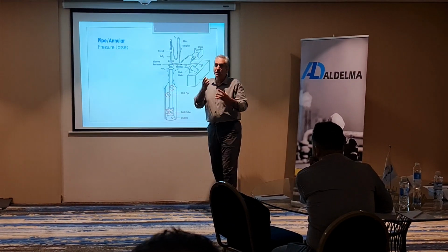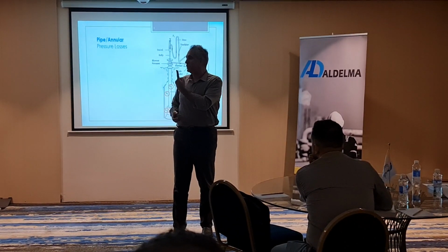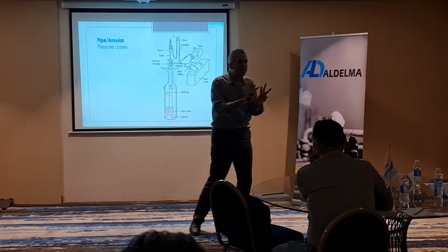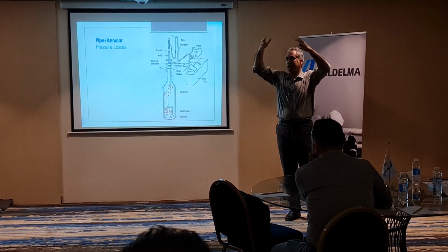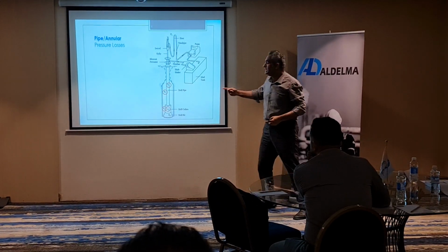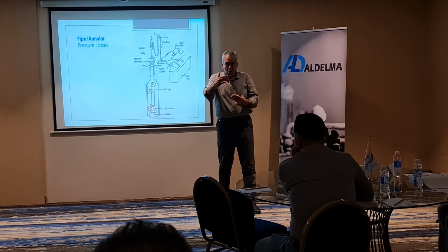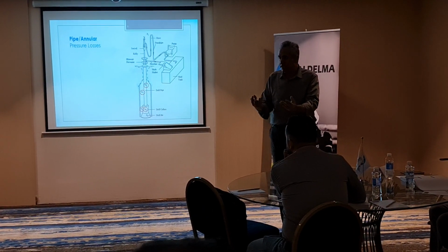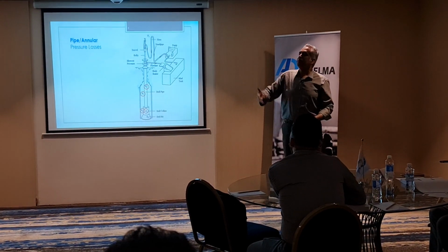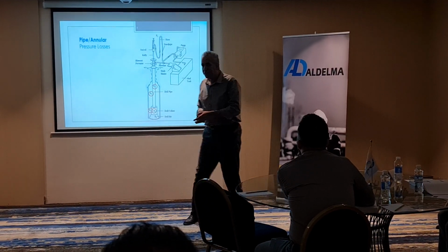The reason we cannot continue drilling very deep, one of them is hydraulics. There are 3 parameters that limit us from going further. The rig capacity, it means the mast strength. Second is the drill string strength. And third is the hydraulics. For example, our pump may be 3,000 psi or 5,000 psi. This looks like this in the industry. We cannot go, for example, more than 90% or 80% of the maximum allowable pump pressure. When we reach this, it stops us from going further.